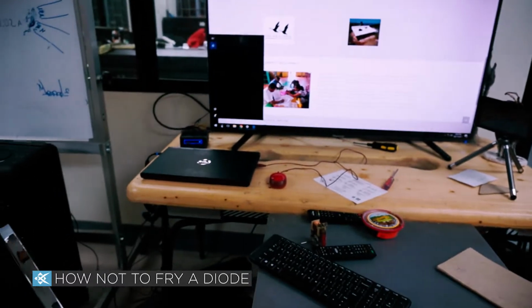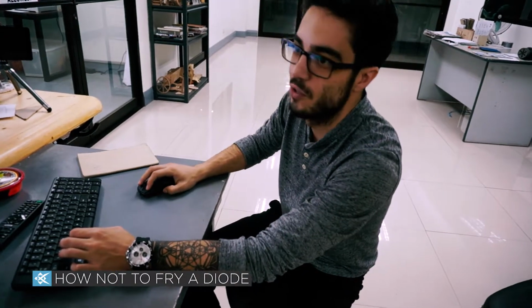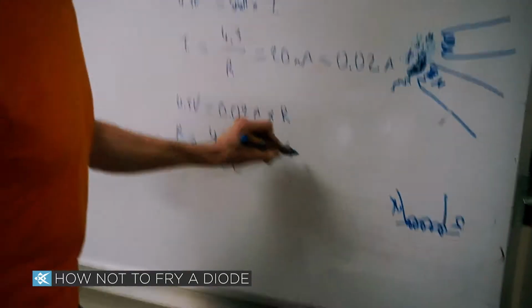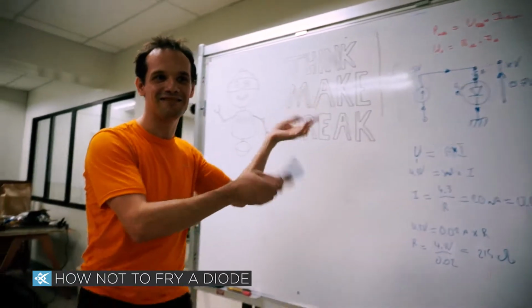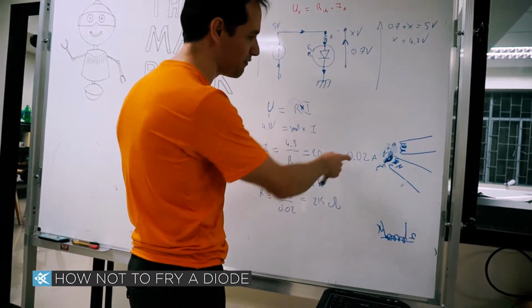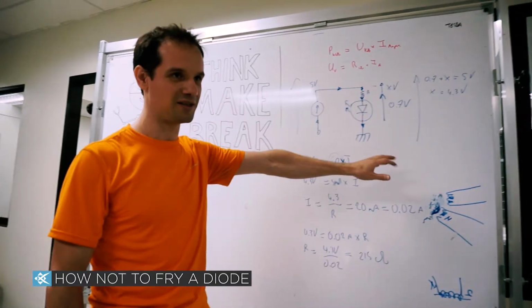and then I need a calculator. Can you actually do this division for me? Isn't this cheating? 4.3 divided by 0.02. 215 ohm. That's it, right? If we put a 200 ohm resistance, you're going to have roughly 20 milliamps there, maybe 21 milliamps or 22 milliamps or something like this, right?